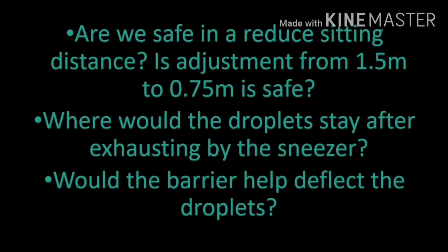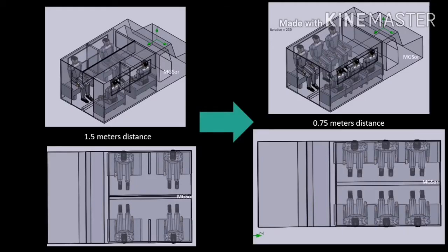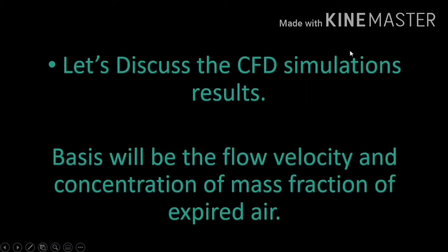So the following should be considered or answered during the simulation. Are we safe in reducing the sitting distance? Where will the droplets stay after being exhausted by the sneezer? Will the barrier help deflect the droplets? I will also be doing a simulation at 0.75 meter distance with an increased capacity from 4 to 6 passengers. So let's discuss the CFD simulation results.